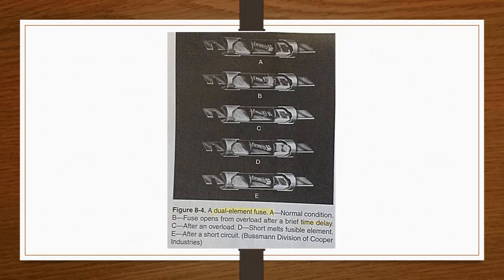A time delay feature is inherent in dual element fuses. However, not all time delay fuses are dual element. The main feature of time delay fuses, regardless of the number of elements, is that they allow for momentary overloads.